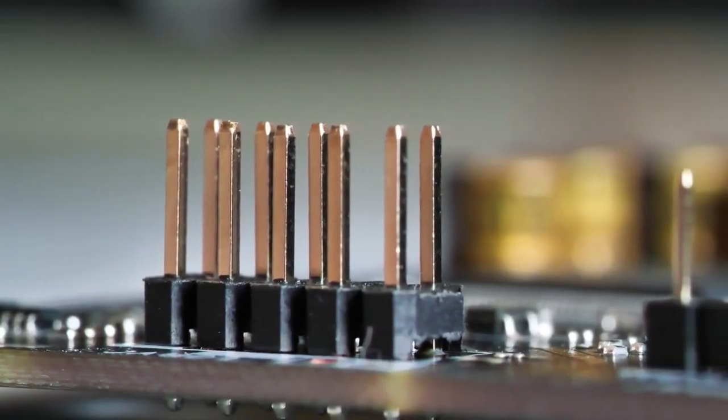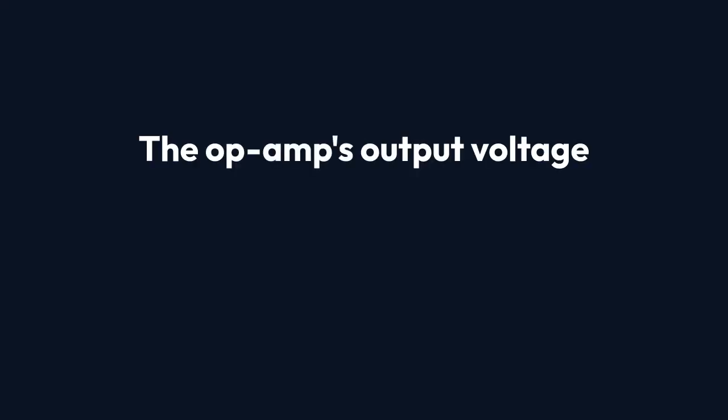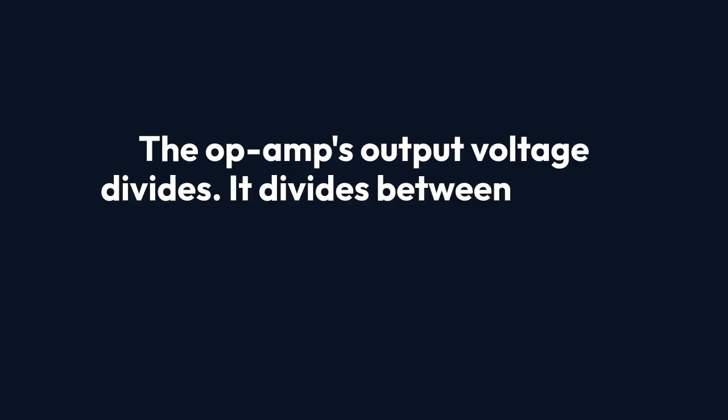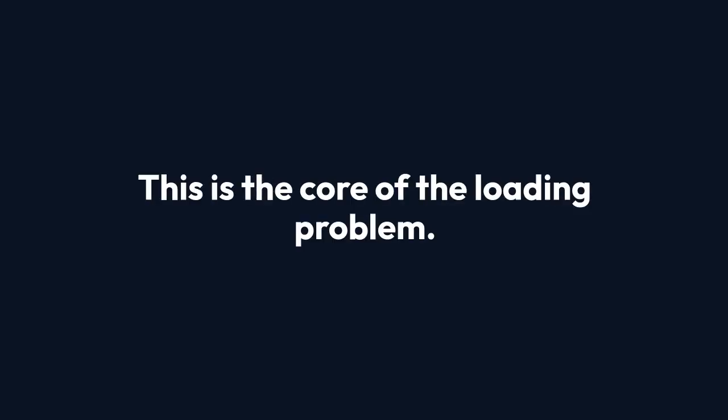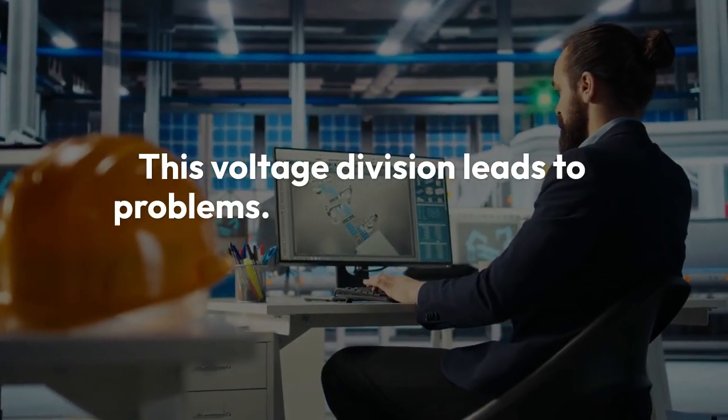Think of it as a voltage divider. The op-amp's output voltage divides. It divides between its own Z_out and the second stage's Z_in. If Z_in is too low, most of the signal voltage drops across Z_out. This reduces the signal reaching your second stage. This is the core of the loading problem. This voltage division leads to problems.